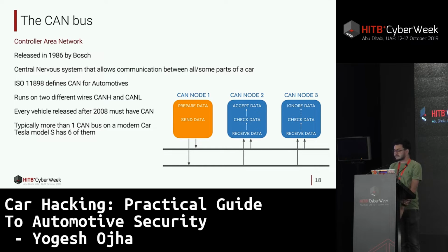The problem could be easily fixed by using one-to-one wiring. Suppose when you have different components like airbag, steering and the engine control, just 3 components. All you can do is connect the infotainment to the airbag, airbag to the infotainment, infotainment to steering, steering to the braking systems. So as the component size starts increasing, the wiring is going to get very messy, right? The more components you have, the more bundles of wire you are going to have.